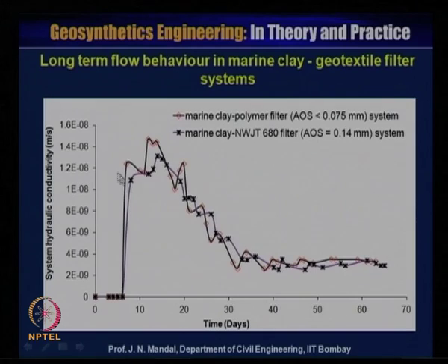So, from this test you can correlate the relation between the system hydraulic conductivity, in meter per second, and time in days. These are the marine clay with polymer filter whose apparent opening size is less than 0.075 millimeter, and also the marine clay with the natural woven jute geotextile 680 filter whose apparent opening size is 0.14 millimeter.